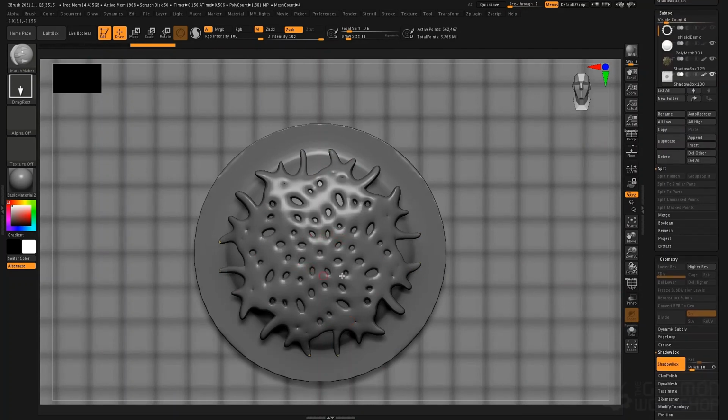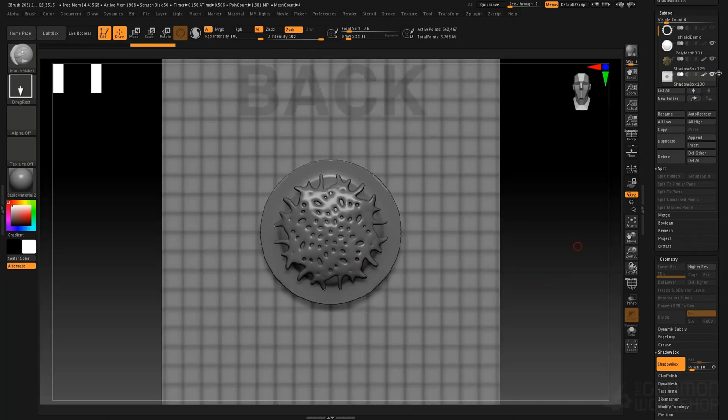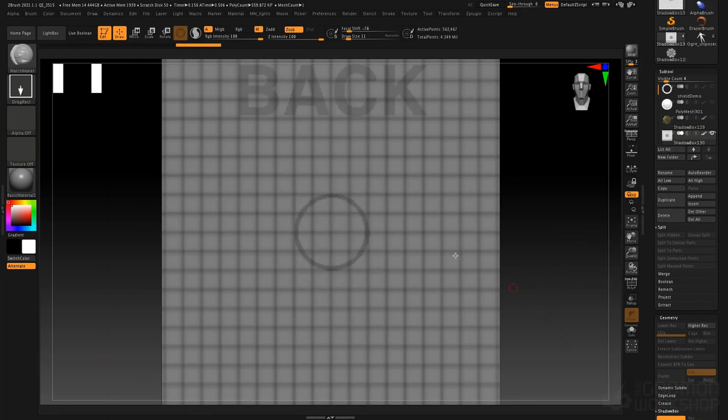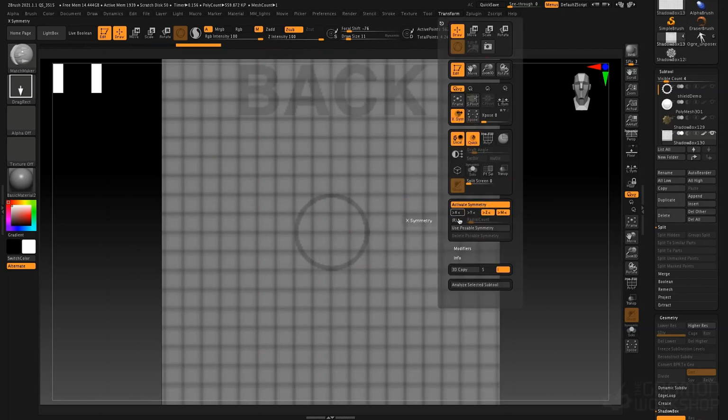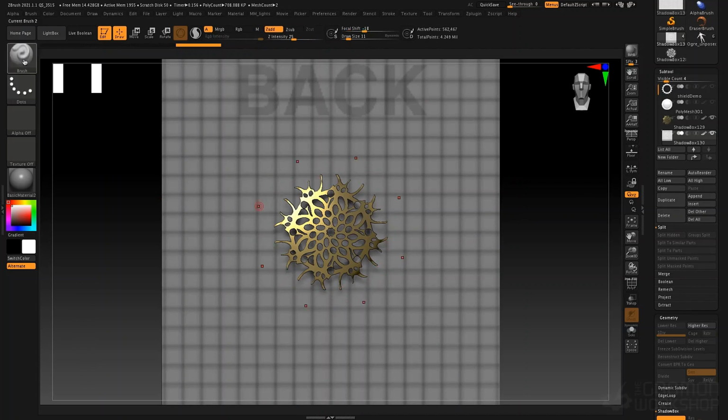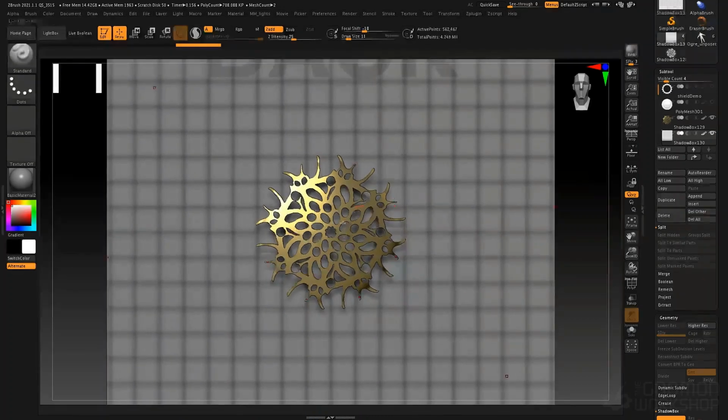And you see it's kind of soft, so I'm going to zoom out just with the F for focus key. And just to make life easier, let's turn off visibility on these other tools for right now. The shadow box is selected, clear my masking. Turn my symmetry back on, and we can go back to transform and turn on Z symmetry and turn radial back on to get our radial symmetry. Now, if I want to use that other piece as a guide, I can turn it on, and I'm just going to press the 2 key just so I'm not on the matchmaker brush anymore, because then you can accidentally matchmake the shadow box, which is kind of inconvenient.